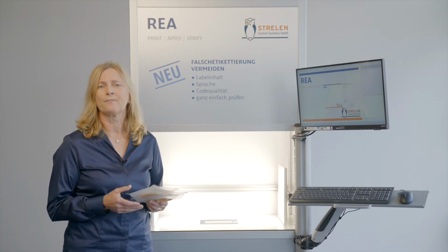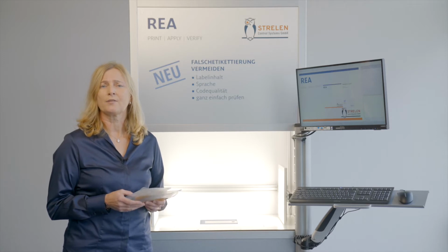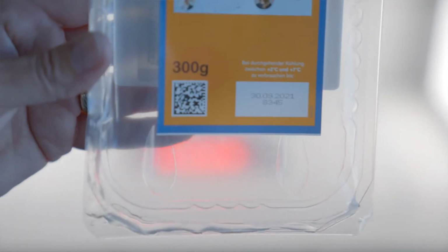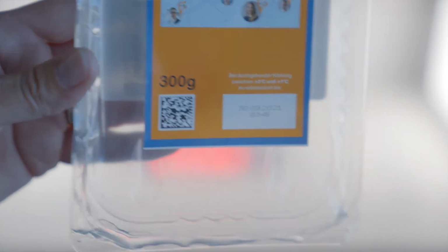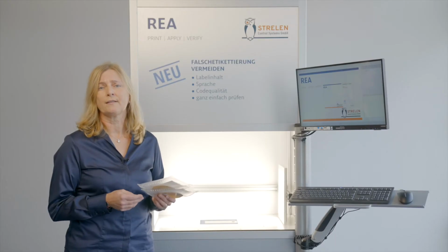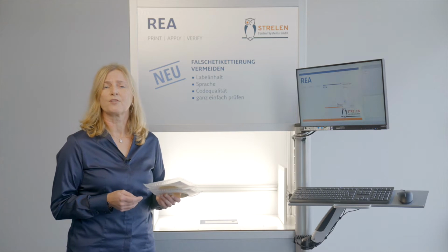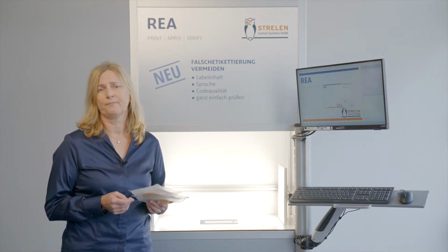Today I will show you how to teach in a new product for random inspections with the LabelTower. The fields on a layout that should be checked for correctness, completeness and readability, and also barcodes or 2D codes whose print quality is to be verified, must first be defined in a teach-in process. For this, a user with the corresponding rights of a setter must log in.